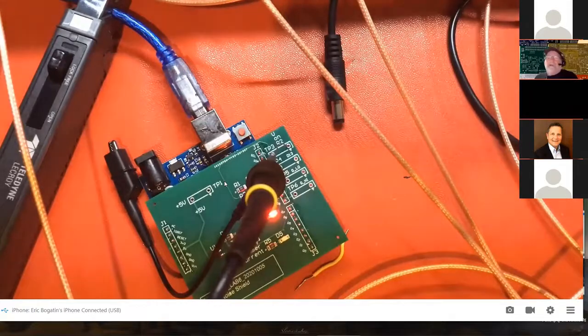So those are the 3 most important figures of merit. The first is the sensitivity and noise, which tells you how small a current you can measure with the shunt method. The second is the bandwidth of the probe, which tells you how fast you can see transients. In this particular example I showed, you got filtering from the capacitors on the board, so most of the frequency components were relatively low. And the third is how much common mode rejection ratio you have, and that tells you how much you can float the differential probe above ground.